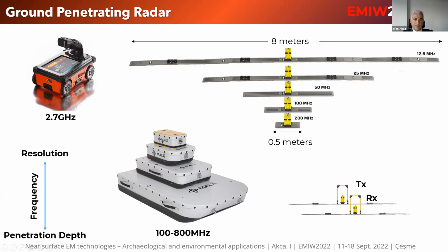At the bottom, you see some different kind of GPR equipment, which are named as shielded antennas. These antennas are in a shield, so they are protected from the EM waves coming from air or ground surface, because we want to record the traces coming from subsurface. So they are shielded, and it provides a protection from noise sources and also the waves not coming from our target.